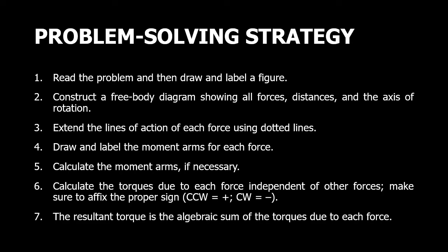Number 6, calculate the torques due to each force independent of other forces. Make sure to affix the proper sign. Counterclockwise is positive, clockwise is negative. So calculate the torques due to each force independently, meaning each force on its own.